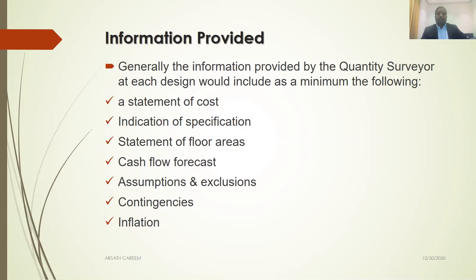Also contingencies. What are contingencies? It's unforeseen work. Normally in the cost plan, in general, we allow it. It's a trend, not compulsory, depending on the nature. Sometimes we allow 10%. It is not a standard. In my experience, we usually allow contingencies for, for example, design development risk. Sometimes client change risk. Sometimes unknown risk, we allow in case to avoid any additional budget being required at a later stage. It is risk elimination, risk management, including the contingency and inflation.